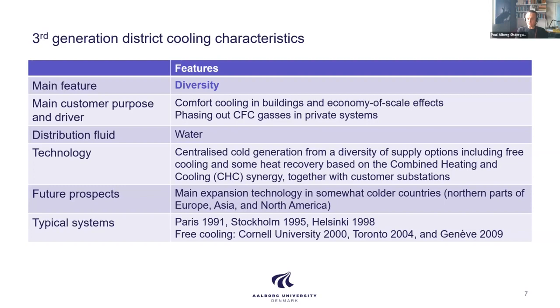You can have heat recovery, combined heating and cooling networks where you're producing heating, and at the same time you're typically also producing cooling, as you will be doing if you have a heat pump, basically. So that's one area where you can pick up some heat. It can also be some natural cooling, meaning you might have a lake or a stream or river with low temperature water, where you can basically take some cooling out of. So you will start playing on a slightly larger keyboard now, different options for cooling.